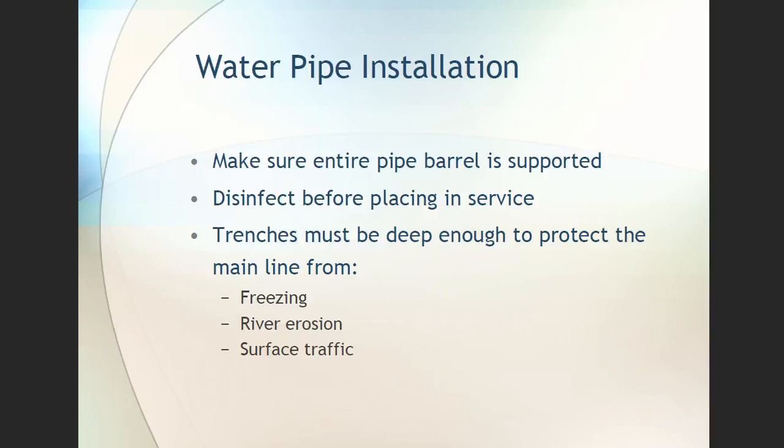So you want to make sure the entire pipe barrel is supported, like I mentioned. You want to always disinfect before placing it into service. Contamination is always an issue. Anytime you're working on a pipeline, it's got to be disinfected. Changing pipe, changing a valve, so on and so forth, small to large.